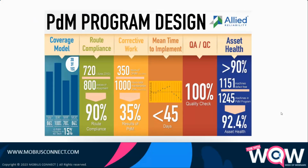So I think this is a valuable slide to show. This is considered to be the gold standard on a PDM program. It helps you understand what that vision is, where the targets are, what you are shooting for as you implement and manage a PDM program. The first coverage model: the 2Q means second quartile coverage, 3T means 3 technologies, and the 15% means that 15% of your overall labor hours are utilized in the execution of an inspection using condition monitoring technologies. That's a good standard to shoot for to start with.